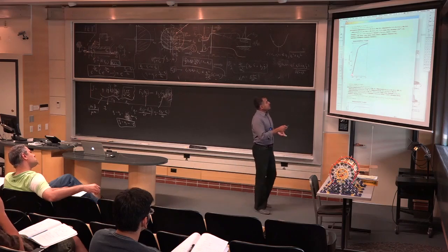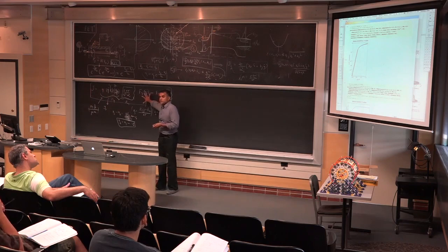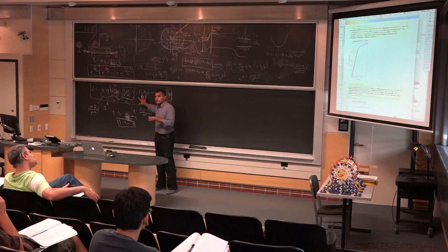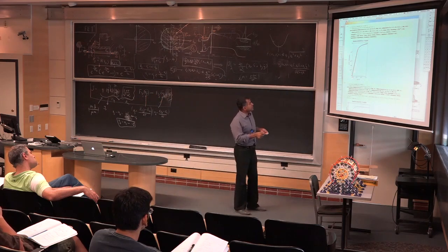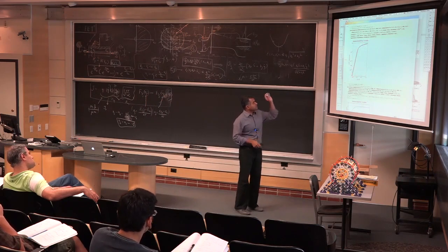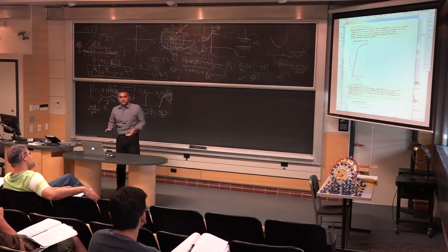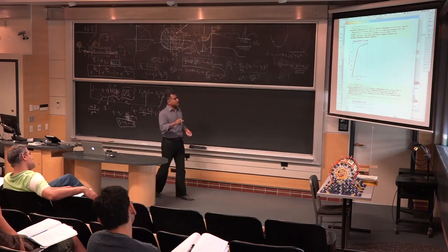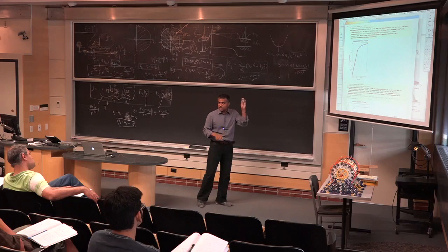So you can see the picture here as a function of the gate voltage. So what are we doing here? We're just plotting this function now as a function of gate voltage at a fixed drain voltage. And at a fixed drain voltage, the current is very low when the VGS minus VT is very far to the left. And you see this picture is a complete copy of the carrier density picture, right? It's a complete copy of the carrier density picture. It's just going down at 60 millivolt per decade, close to that, and then once you turn on, it kind of starts saturating in some sense. Right? But it's not a saturation.